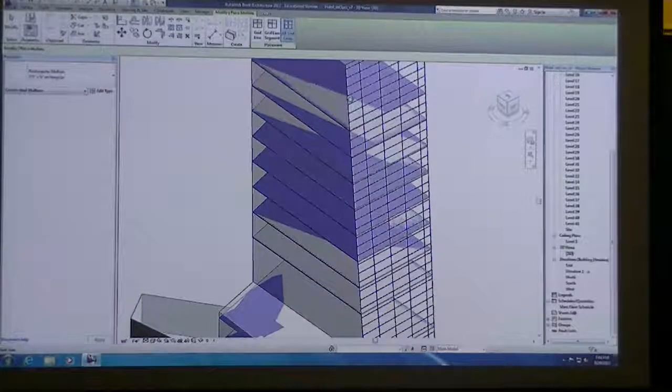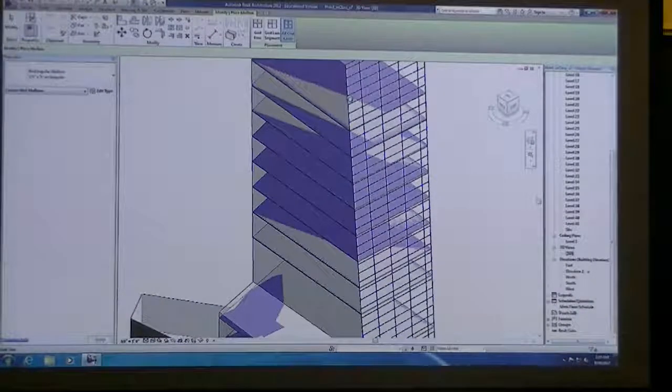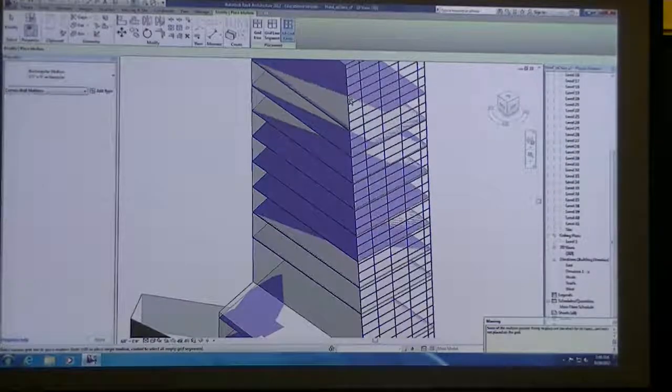And it might take a moment because it's trying to place a mullion on every single grid line. To be honest, the curtain panel pattern-based systems that we've already developed, of course they don't have to be as complex as we tried to do with our bridges. As long as you have a solid frame around the exterior, you're going to want to make sure in your curtain panel pattern-based form, you also have a glass component. You could divide up your mass and then apply that curtain panel all throughout your facade system.